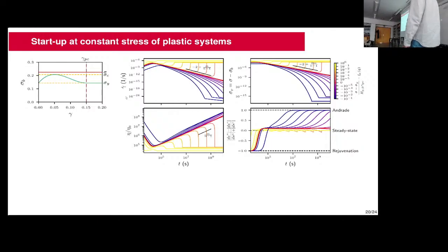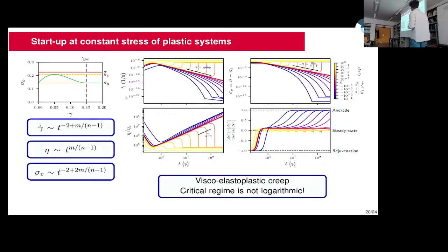And again, in this case, you have a double contribution. So you have viscosity and deformation of your solid system. But here, it's not just the deformation of the particles themselves. It's some plastic deformation that corresponds to structural rearrangement of the structure of your yield stress. And we find some other exponents.